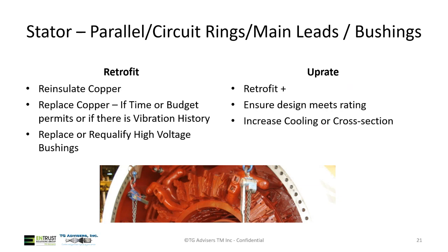So that being said, you want to make sure that all of your new conductors or retained conductors can handle that new load. You may want to increase the cooling to it or the cross section, so that it can meet that rating.